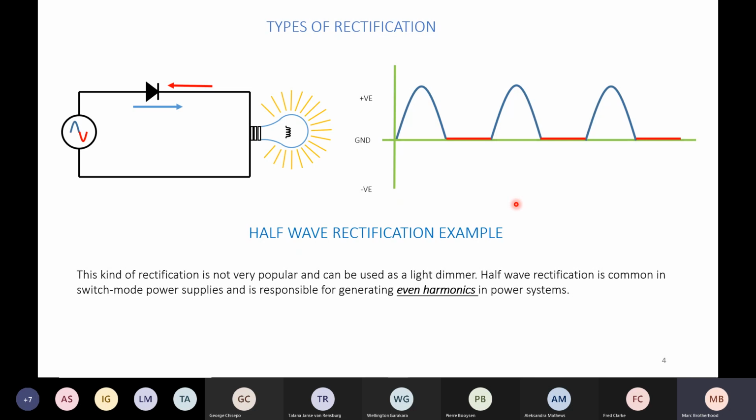generating multiple different voltages. Even on our VRV, not our VRV, anything inverter driven on the Daikin equipment also goes through what we call switch mode power supplies. We have different voltages supplying the pressure transducers, the temperature thermistors, the fan motors. All of that needs different voltages, all chopped up from one supply voltage of 230 volts. So that's what a switch mode power supply does.